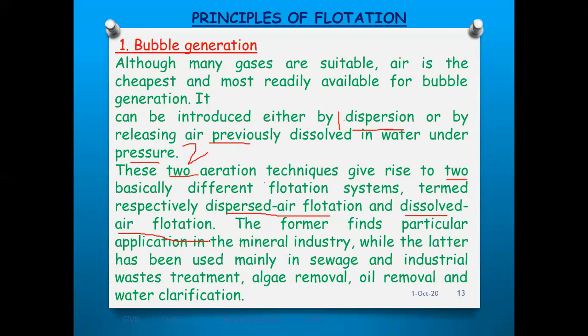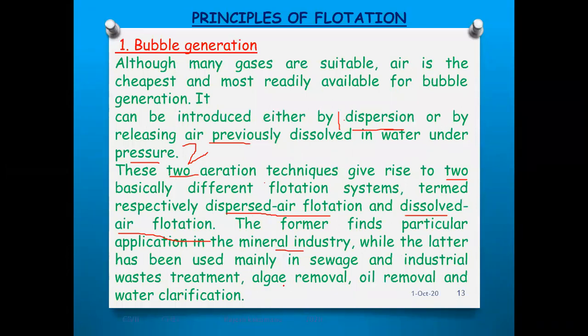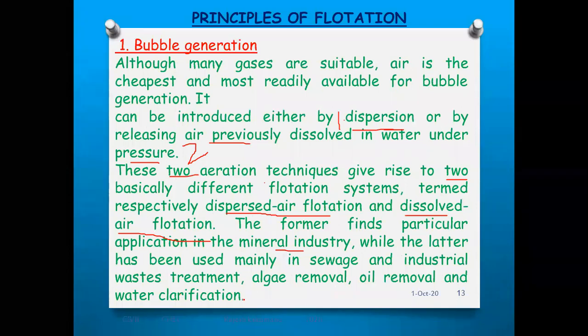So whenever you use the dispersion method and the water pressure method, two basically different flotation systems come up. What are those? The first one is dispersed air flotation, which is used in the mineral industry. And the second one is dissolved air flotation, which is widely used for industrial waste treatment, algae removal, oil removal, and water clarification. Right? Yes.